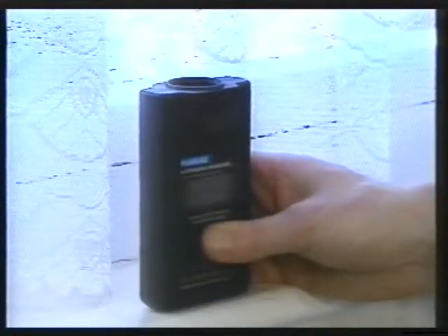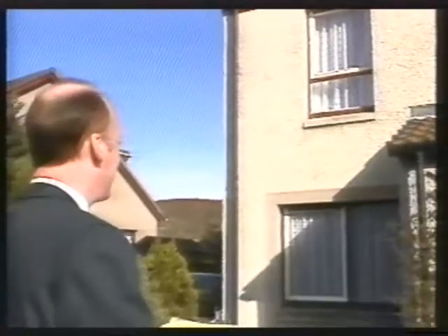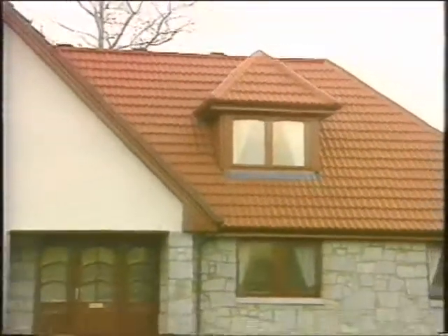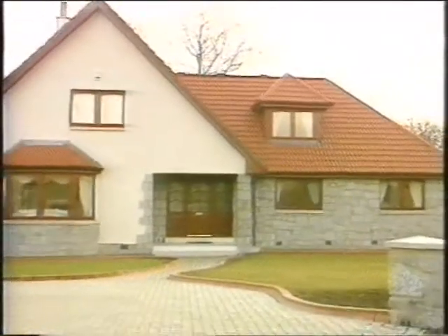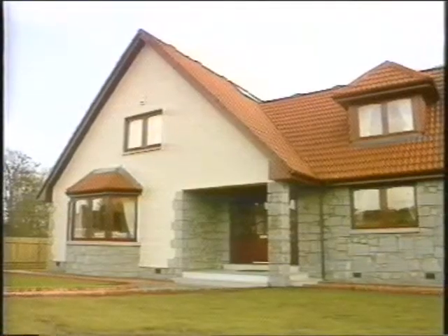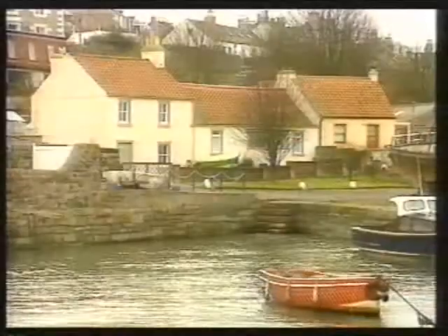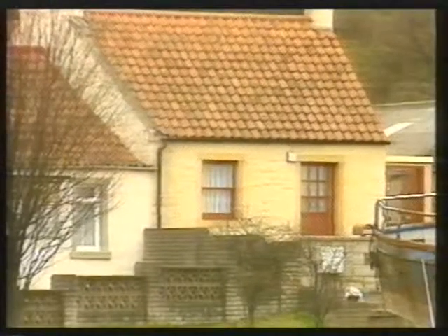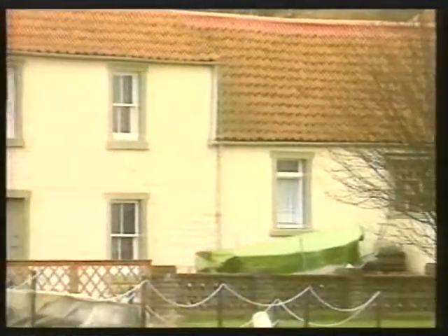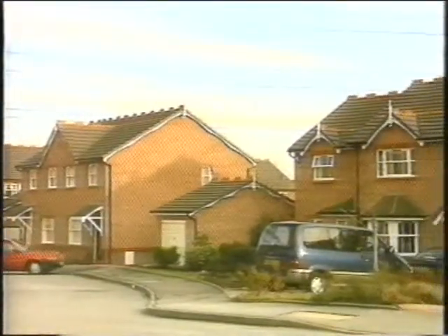This will depend on many different things: how the place has been built, the materials used, their thickness, and the difference in temperature between inside and outside. Construction methods and materials vary between different house styles, but more importantly, the area for potential heat loss can vary quite considerably. Look at the difference in roof, wall and window area between a big detached house, for example, and a small terraced cottage or a flat. Figures are available which give average outside temperatures. These have been used to produce a recommended external design temperature of -1 degree Celsius.